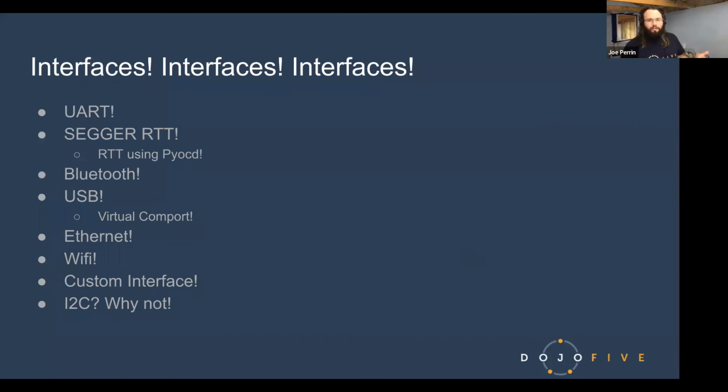So somebody says, oh, we don't have UART when we have the plastics on. Great. Let's move over to RTT. Let's move over to Bluetooth, right? That's not a reason not to have a CLI, because the interfaces might change during the life of the project.